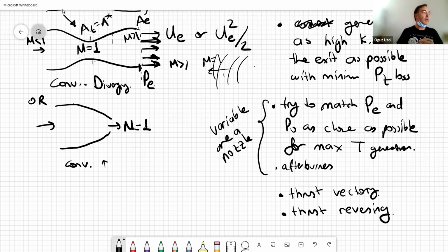That's nice. We need cooling of the nozzle walls. Plus, that raises the temperature of the fuel a little bit. That's also nice because it helps me to spend less pumping energy when I'm trying to inject into the combustion chamber. So it's a win-win situation. That's how we cool the walls of rocket engines. If you check the Raptor engines of SpaceX, it's like that. If you check the engines for Apollo, it's like that. It's just generally a well-established technique.